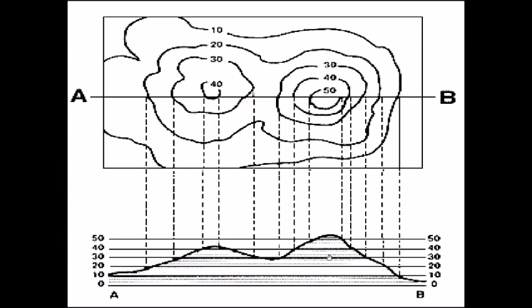So like we see over here, we have two hills, and when you draw the contours, these hills are shown in a section view. That means you're looking at them from the front in actuality. So they'll have a conical shape, and that's why you have a contour which is circular, and two hills, so that's why two sets of circles, and then you have bigger irregular circles since the elevation then gets similar with both the hills.